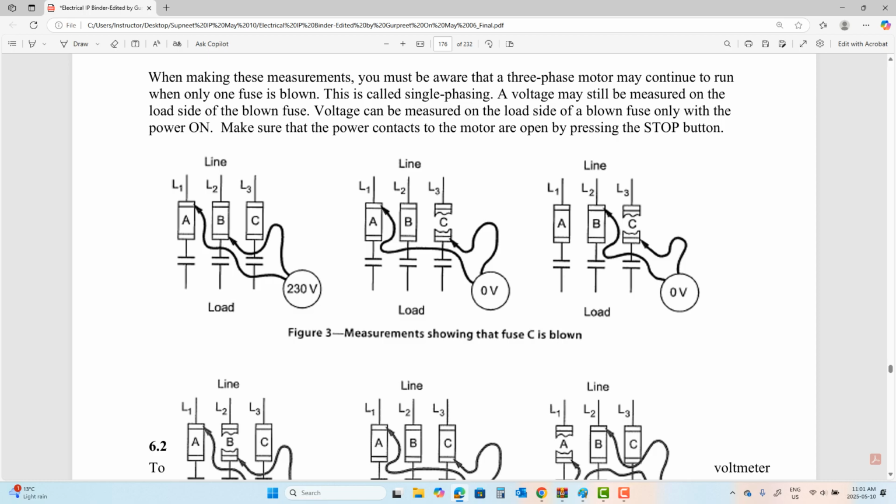What will be the reading on the other side of the multimeter? Nothing. Why? It's a hanging pin. It's not connected to ground. You're not defining the potential difference between line 1 and ground. It's a hanging pin. He didn't show a ground. So don't get confused. The output will be 0.